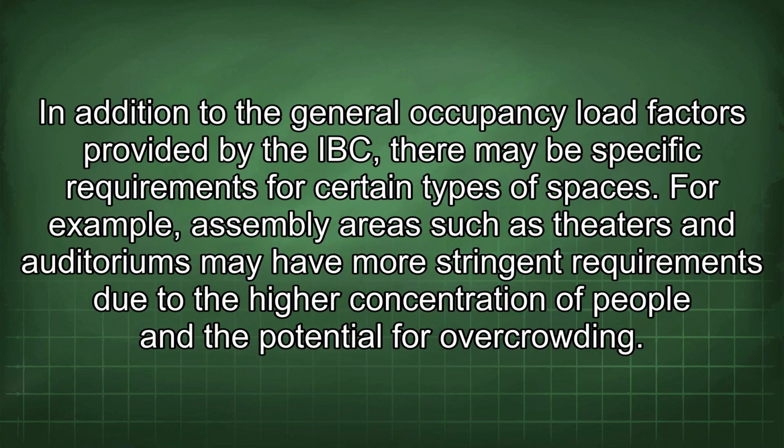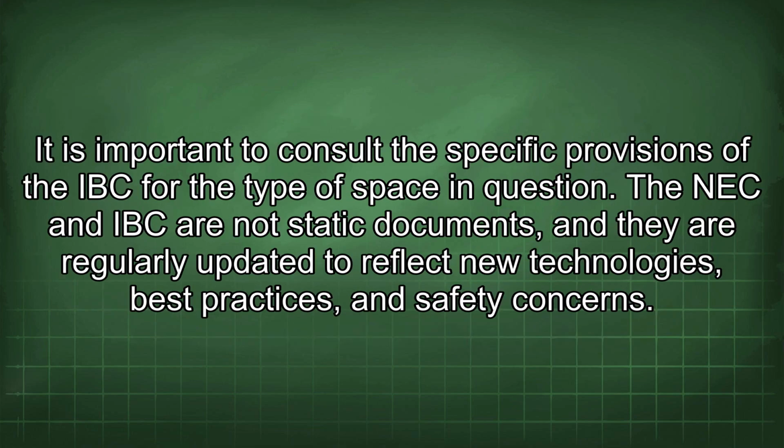In addition to the general occupancy load factors provided by the IBC, there may be specific requirements for certain types of spaces. For example, assembly areas such as theaters and auditoriums may have more stringent requirements due to the higher concentration of people and the potential for overcrowding. It is important to consult the specific provisions of the IBC for the type of space in question.